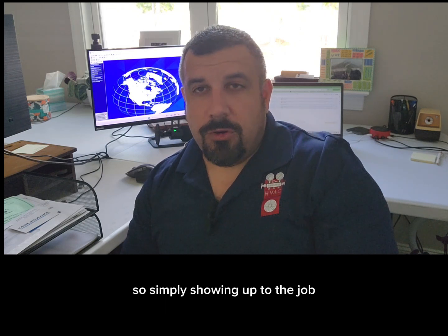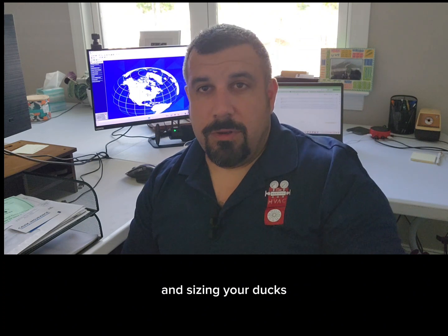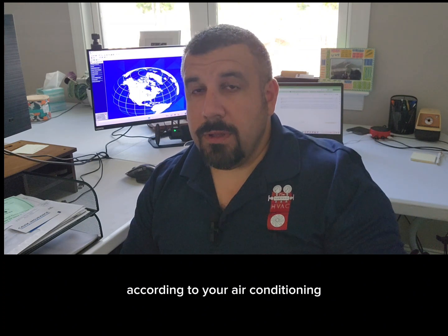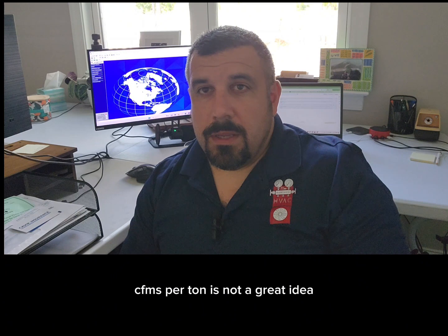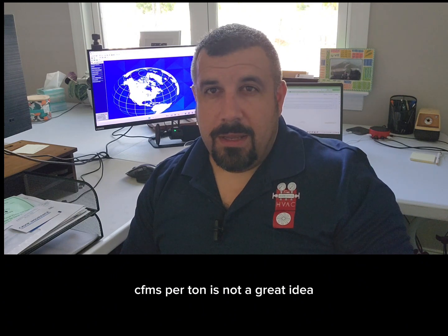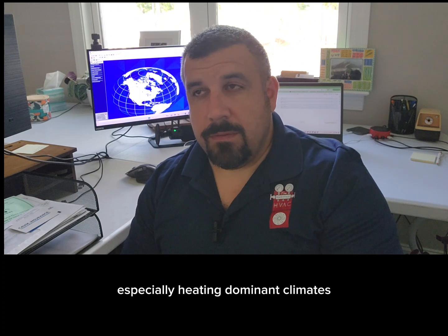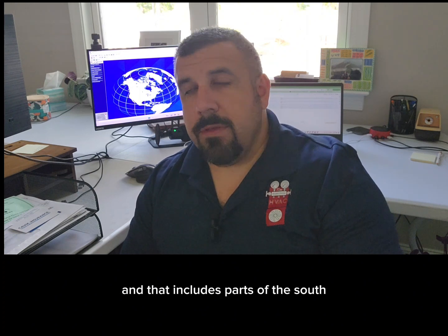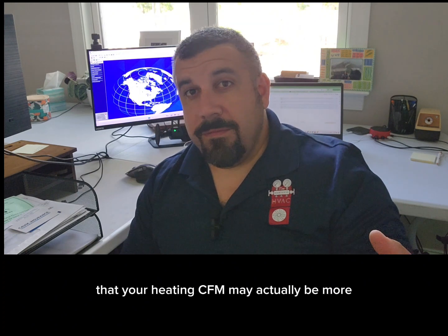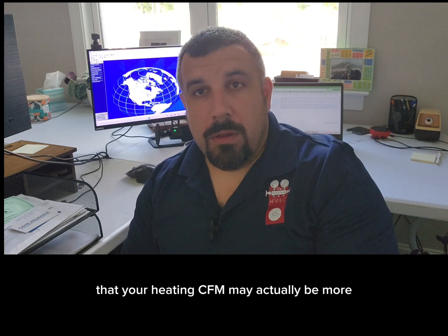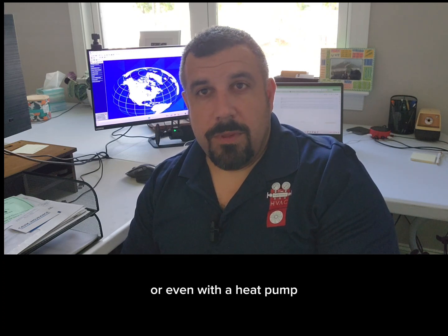So simply showing up to the job and sizing your ducts according to your air conditioning CFMs per ton is not a great idea, because in a lot of places, especially heating dominant climates, and that includes parts of the South, your heating CFM may actually be more with a condensing furnace or even with a heat pump.